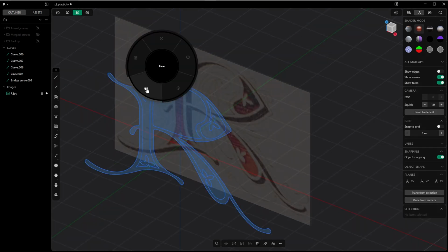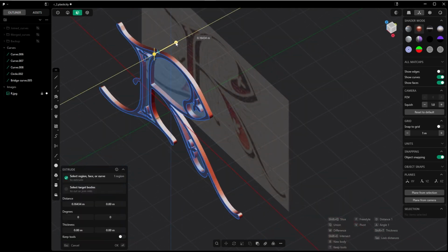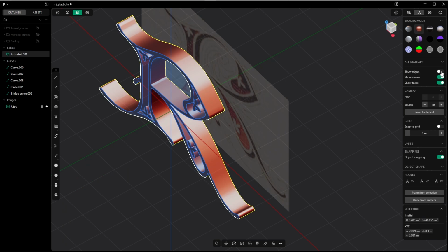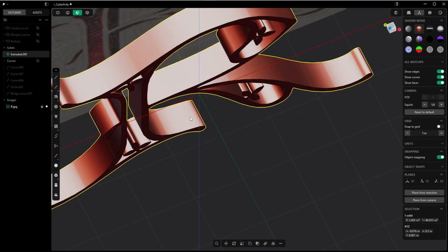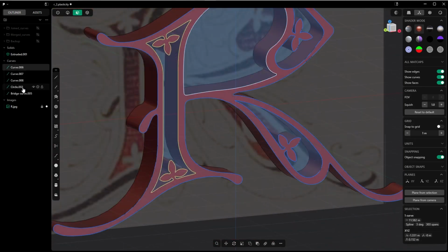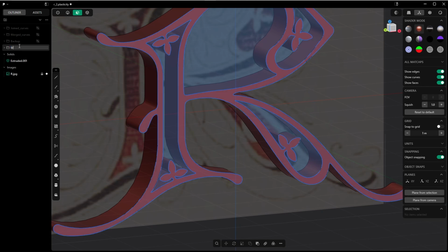Okay, now in face mode we can extrude this guy and see if everything goes smoothly. Let's extrude the distance of 0.6. Press OK. And check for show edges. We want to see if there are any edges. So as you can see, there aren't any redundant edges whatsoever. Let's take these curves. In my former attempts, I already made a folder called merged curves. So that's why I will call these guys merge curves 2. Super creative. I deactivate these curves.